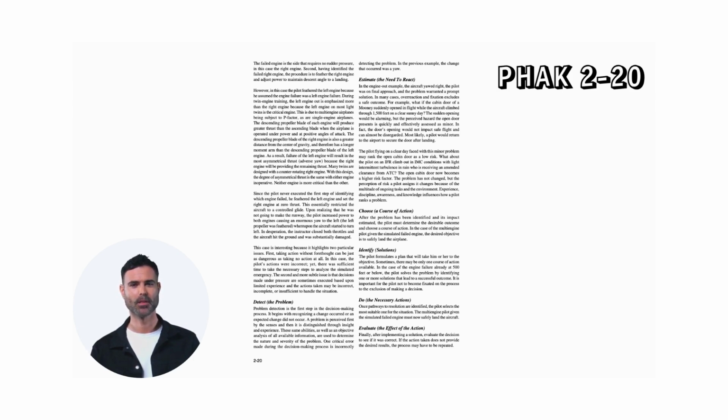Sometimes, there may be only one course of action available. In the case of the engine failure already at 500 feet or below, the pilot solves the problem by identifying one or more solutions that lead to a successful outcome. It is important for the pilot not to become fixated on the process to the exclusion of making a decision. Do the necessary actions. Once pathways to resolution are identified, the pilot selects the most suitable one for the situation.